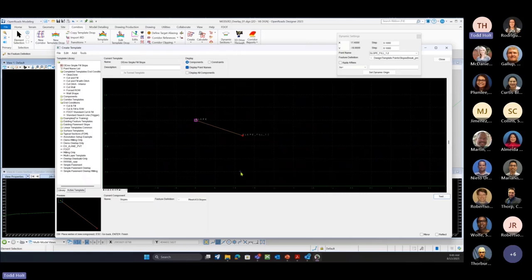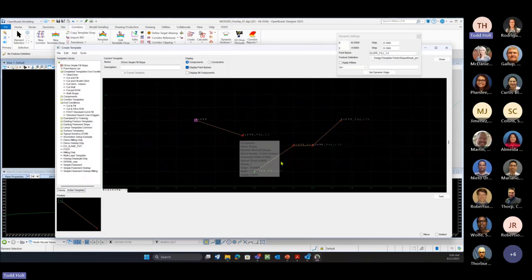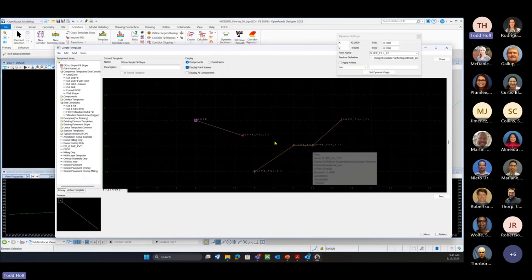constraint component. So say our end condition that we're drawing in there, so we're going to draw an end condition. So we have a slope that's going to go up here, but then it's getting too high. That slope's getting too steep, so we need to flatten that out. So we're going to create a benching in that slope. And I don't want a closed shape. So we want to create something like this, that we can set in the end condition, that we can build the end condition, and then we could just put that slope in here as we could flatten out that slope so it's not so tight